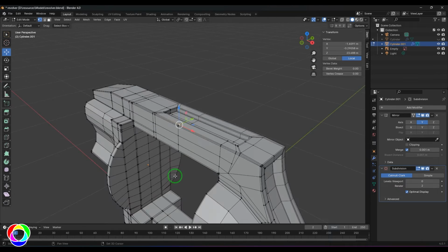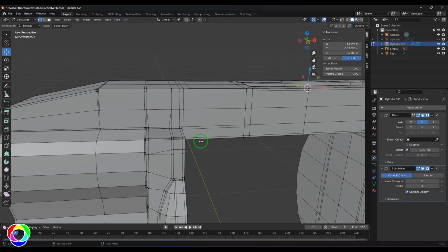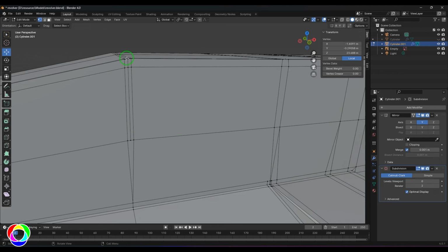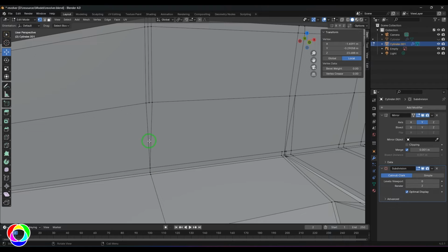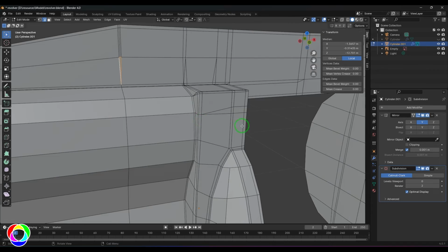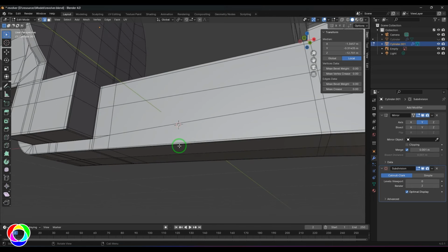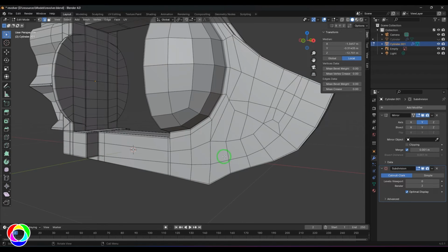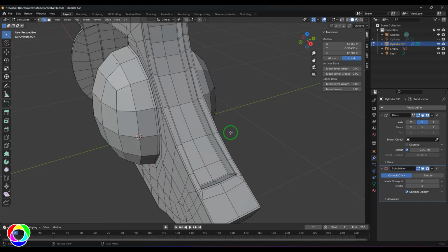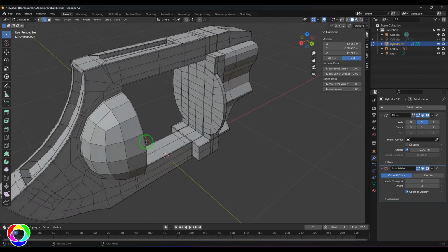Okay, so those lines are placed here and there, and after adding lines, this model can become more complicated. So in cases I have to bring 3 lines into one line, and when we apply smooth, it becomes even. In fact, this is a quad. So if you could see here, 1 2 3 4, this is a 4-sided model. So I have done that way throughout the model. Sometimes I've kept triangles on planar surfaces, and triangles are generally not recommended, but in hard surface modeling, if you end up keeping a triangle, that should not create a big problem at all.